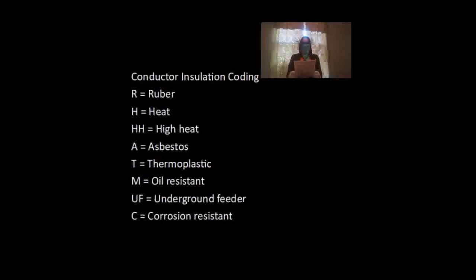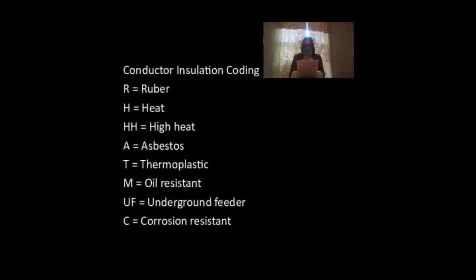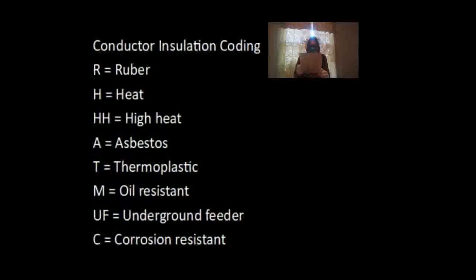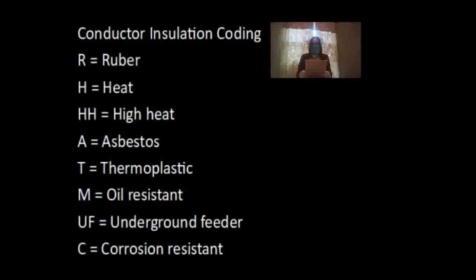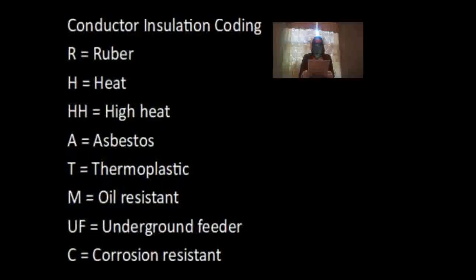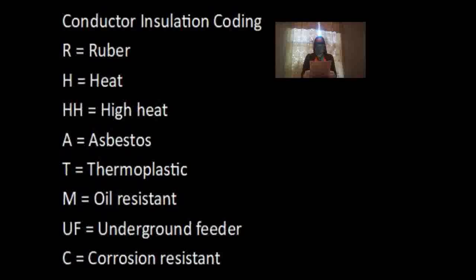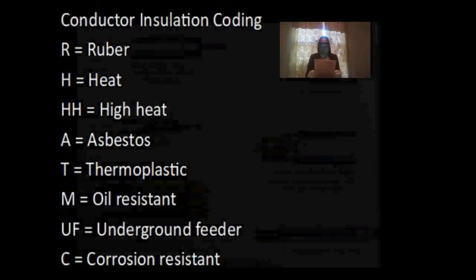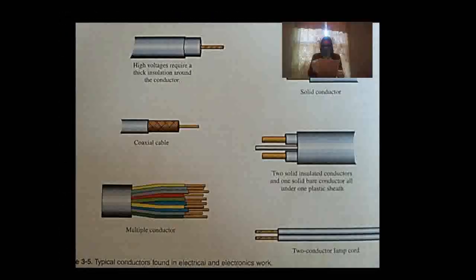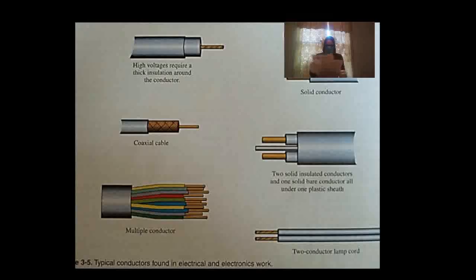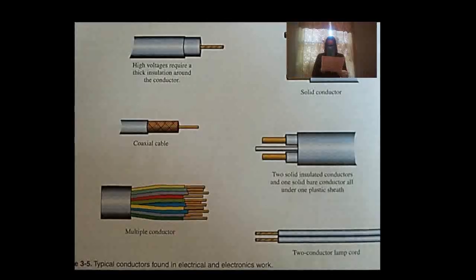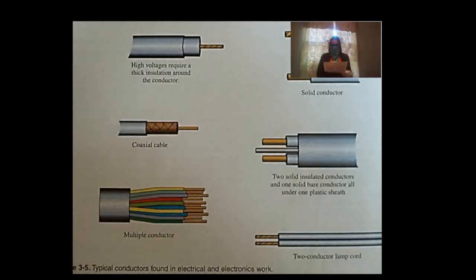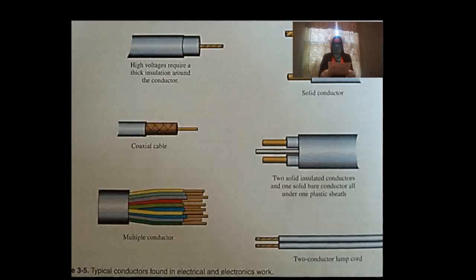There are many types of insulation commonly known today. These materials include thermoplastic, neoprene, Teflon, nylon, and polyethylene. The type of conductor insulation is determined by the application of the electrical system. In determining insulation type, many factors must be taken into consideration. Some questions one might ask would include: will the insulation be exposed to extreme heat generated by an industrial furnace or the extreme cold of a freezer in a food processing plant? Will the insulation need to withstand exposure to acidic vapors in a chemical plant or wet acidic soil? Will the cable be exposed to oil from manufacturing equipment? Will the insulation give off toxic fumes if burnt? Will the insulation in a building affect the breathable air to its occupants?